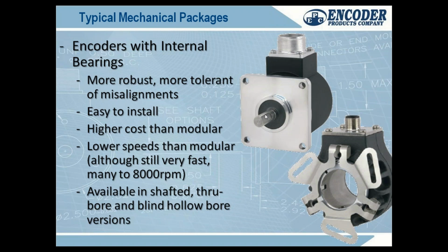If you have it, let's say this is on, what's an example I did? A concrete vibration machine. It actually vibrates concrete at specific frequencies to make a very specific textured concrete. Pretty interesting. That machine, man, it can vibrate. So they ran with through bore encoders that sit on a sheet metal flange. So this bolts on the shaft. Now the disc is hard mounted. It's going to move with the shaft. But the housing of the encoder is going to move with it as well, and it's going to shake on this extremely flexible spring.